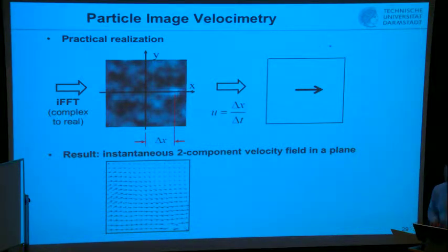And then the idea is, if the number of these spurious vectors is acceptably low, let's say 5% or so, you use the information from the neighborhood to smooth them out. In a thorough description in a paper, you should find some statements about the percentage of these erroneous vectors. If this is not given and the vector field looks very nice, be careful.